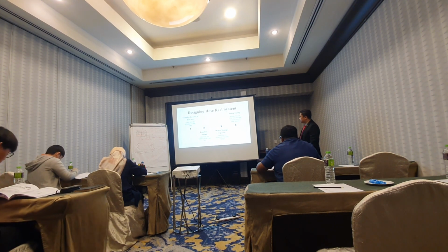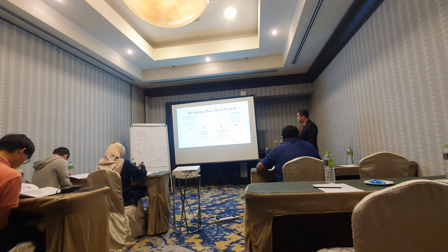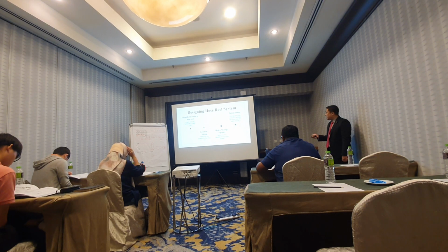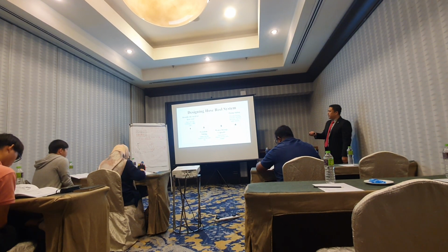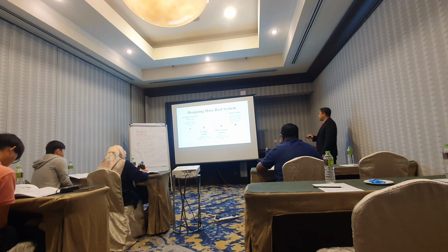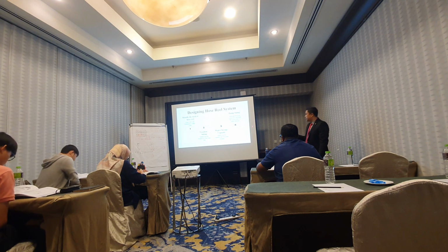And after that, we need to set the location of the hose reel by determining the location for the hose reel itself. And then we have to have the water capacity, how much the water capacity is. I've done it here, so this is how we calculate, but we can have the maximum capacity of 7,200. And the pump sizing: the arrangement of the pipe route, and calculate the pump size for the water delivery.